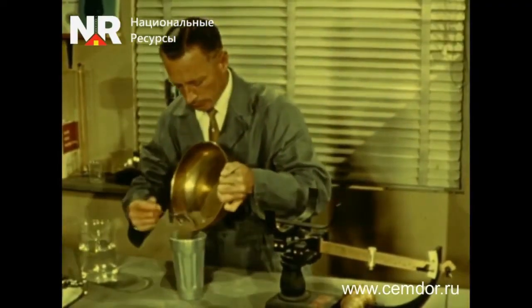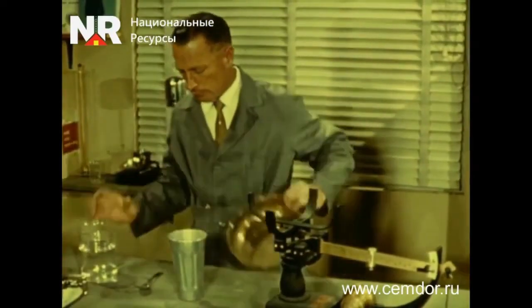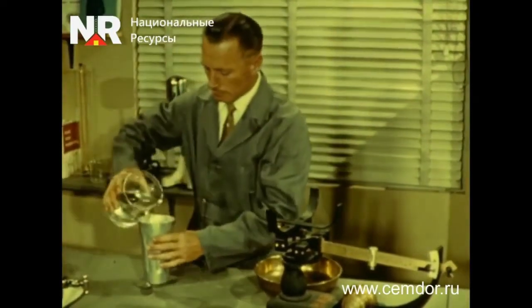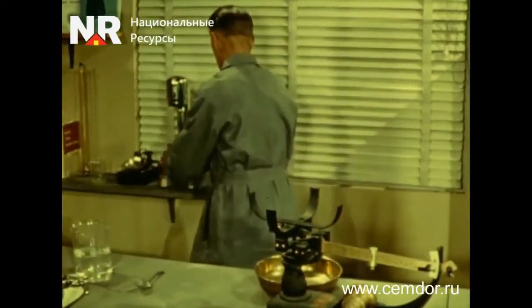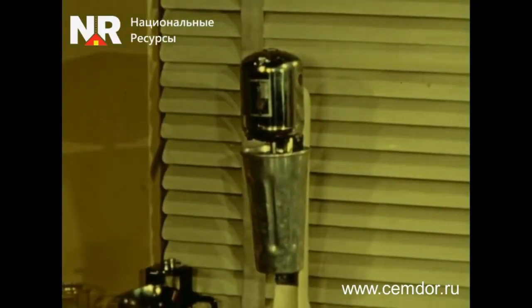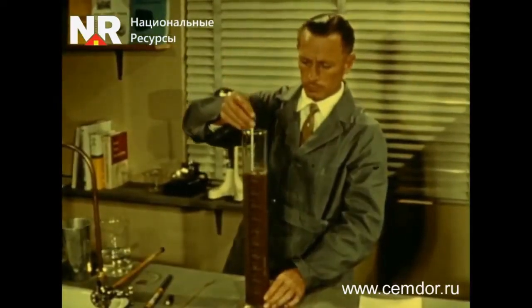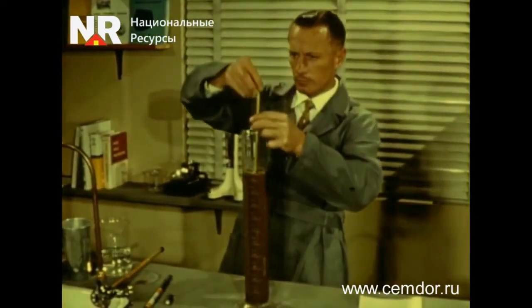The residue on each sieve is weighed. The distribution of the finest soil particles is determined by the hydrometer method. For this, the residue is mixed with water using a high-speed mixer. Based on each measurement with the hydrometer, the total soil content must be calculated using a special formula.